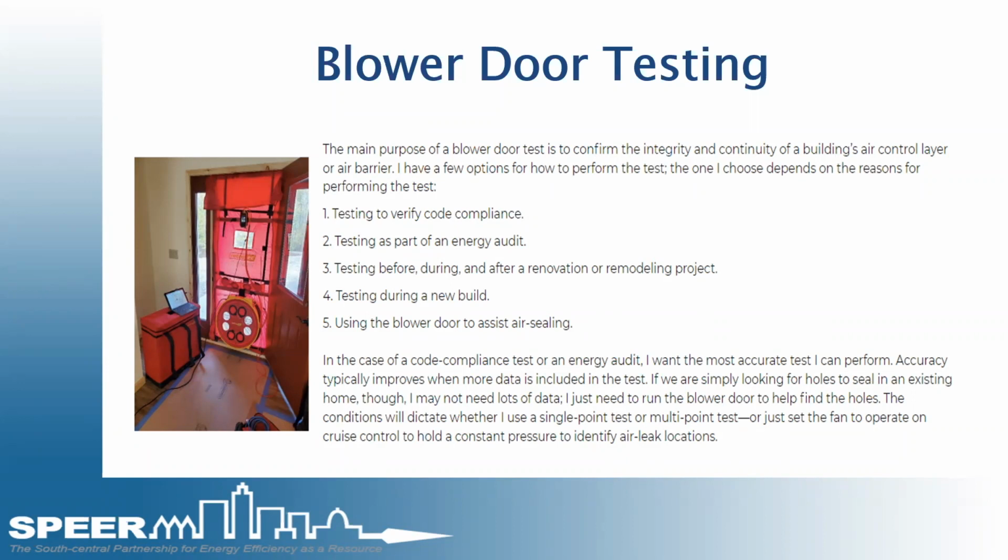I'm not going to read all of that slide. That kind of just goes through the compliance testing. But when the rater or inspector does the testing, you can't really tape up supply and returns. You can't tape up the openings around sheetrock penetrations like sprinklers. You can't tape around bath fans. You have to leave those things as is. It has to test out as if the homeowner was occupying the home and how it's going to perform on an everyday basis. You can't seal things up to manipulate the test. That's not what the test is for.